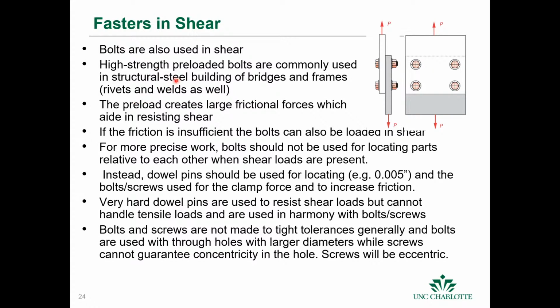Okay, and so in this case, when you preload these bolts, you torque them down, you actually create large frictional forces between these plates, and those frictional forces are beneficial in preventing shear. Okay, so if you have an applied load and these bolts are torqued down really well, then the material is going to pick up the majority of that shear stress.